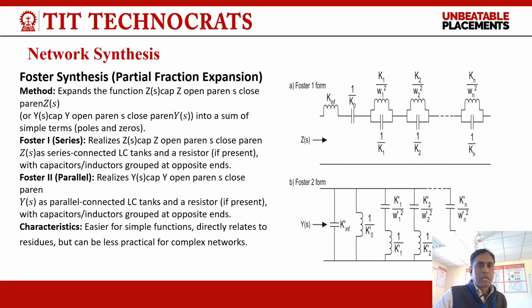Foster 1 realizes Z(s) as series connected LC tanks and a resistor with capacitor or inductor grouped at opposite ends. If we talk about Foster 2, it realizes Y(s) as parallel connected LC tanks and a resistor with capacitor and inductor grouped at opposite ends.